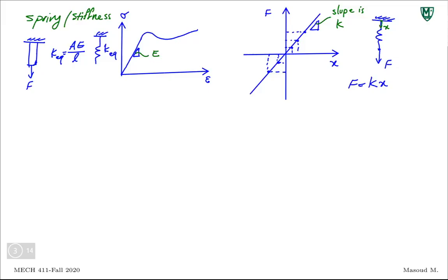One more case would be, well, you have a cantilever beam in this way. The force is applied here. Well, we talked about this too. If a force is applied here, we know the deformation would be in this form, delta. So we can apply different amounts of force or a specific amount of force, as long as it's not so much that it makes it nonlinear. It's a small amount, so the deformation is not that much. We can measure delta. Once you measure delta, this would be FL cubed over, I think, 3EI, we said. And from there, you can find E again.